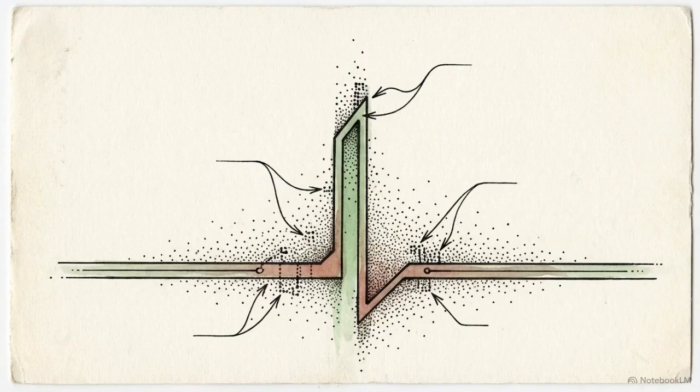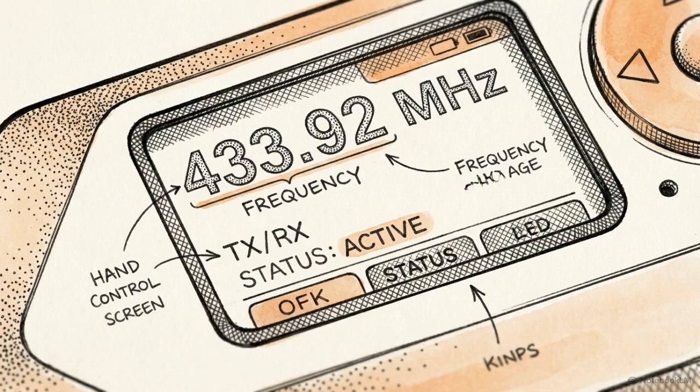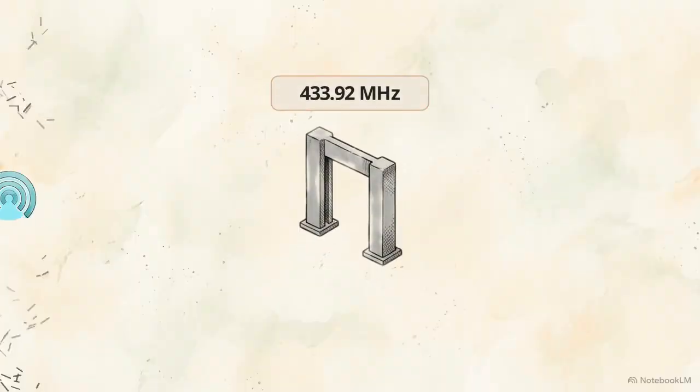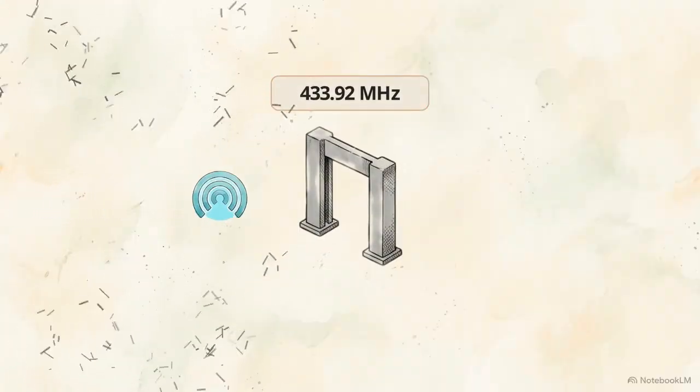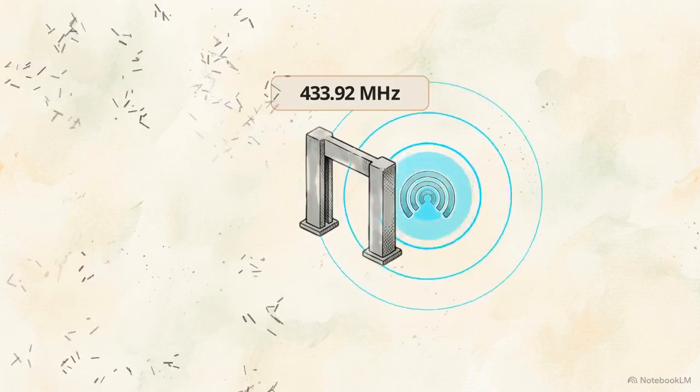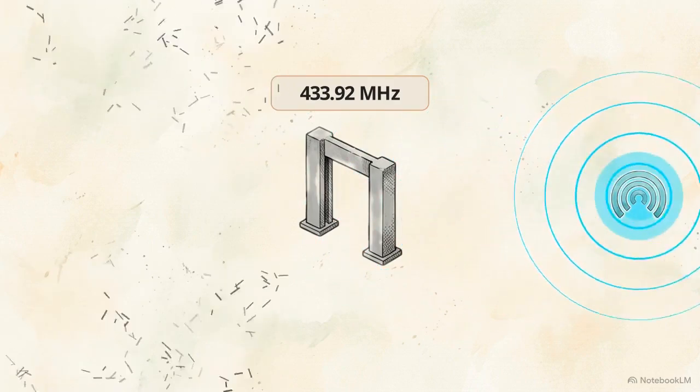You will see a prominent frequency spike appear on the Flipper's screen. Note the exact megahertz value displayed at the peak of that spike. Locking in this specific value acts as a precise filter. It allows you to isolate the targeted data transmission from the constant hum of background noise.